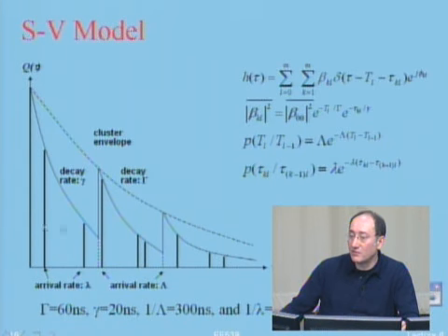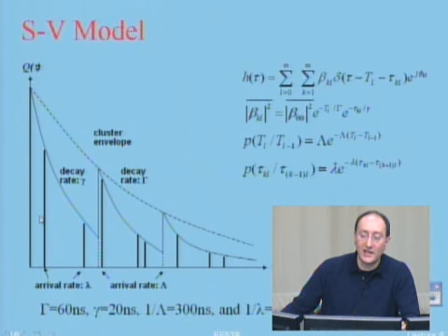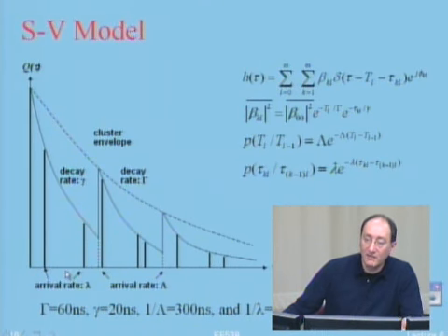And the PhD student who worked on that was Ganesh, and he just actually showed that in indoor, very similar to the outdoor, arrival of the paths form a log normal distribution. Inter-arrival is not Rayleigh, is the so-called modified Rayleigh, which also is called delta K model.